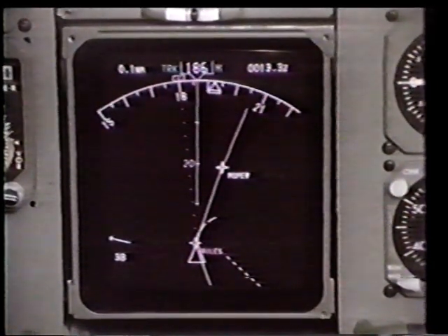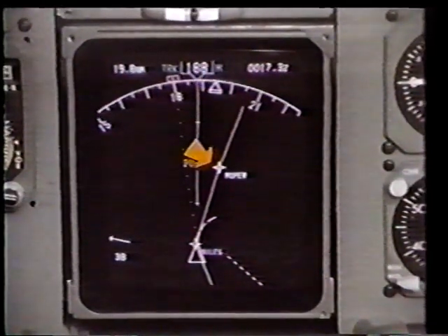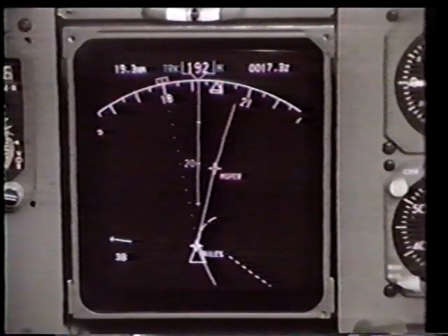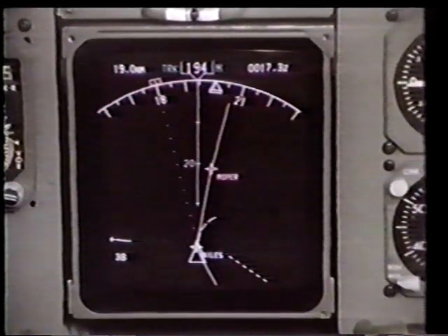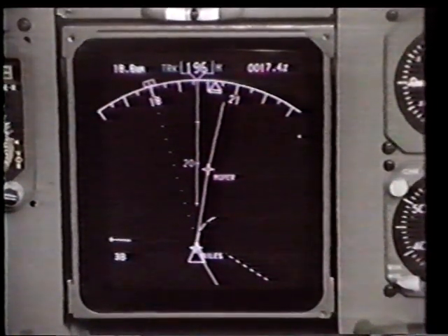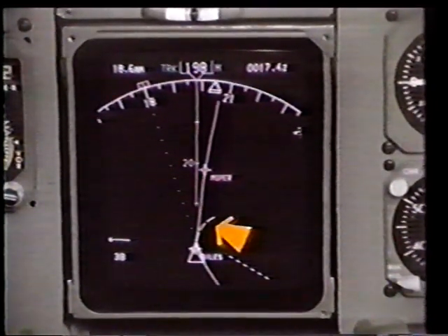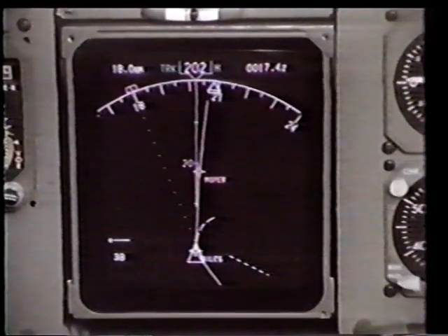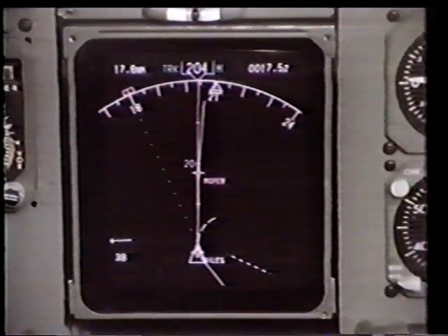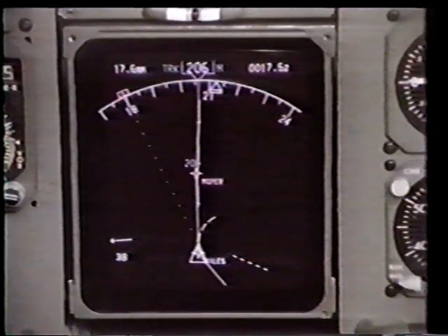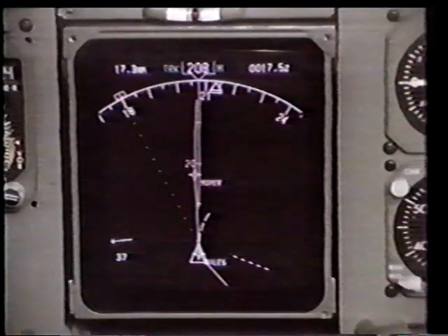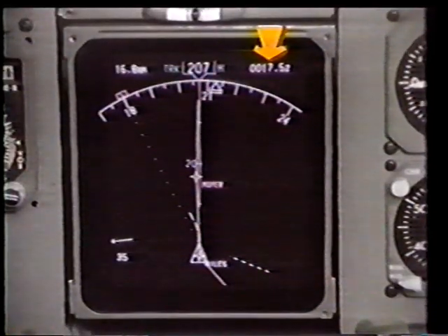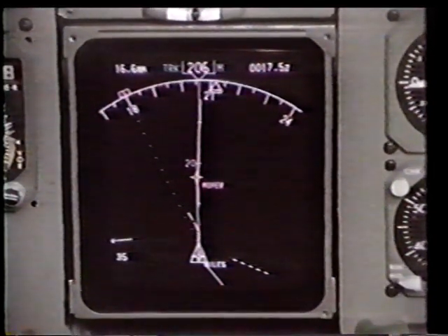When a waypoint becomes the next one being flown to on the flight plan, its color changes. Flying the track line cursor over the flight plan route simplifies the course tracking task for the pilot. During turns, a trend vector displays projected flight path based on bank angle and ground speed. Up to 3 segments may be shown depending on map range, with 30, 60, and 90-second positions indicated. Distance in nautical miles and ETA to the waypoint currently being flown to on the flight plan are also shown.